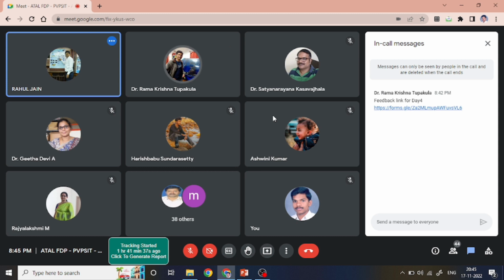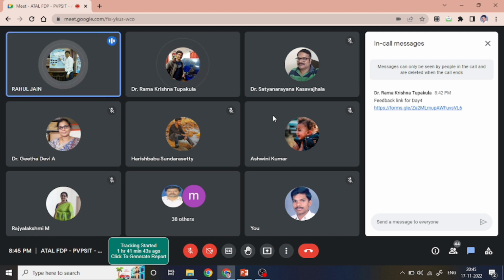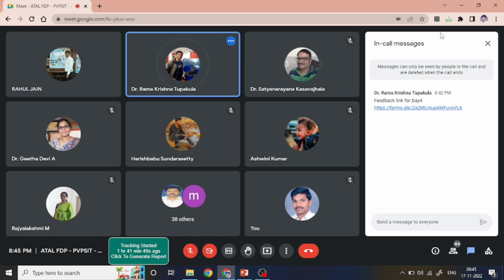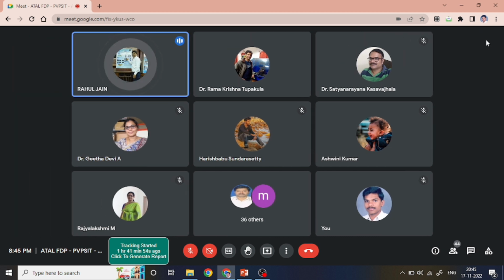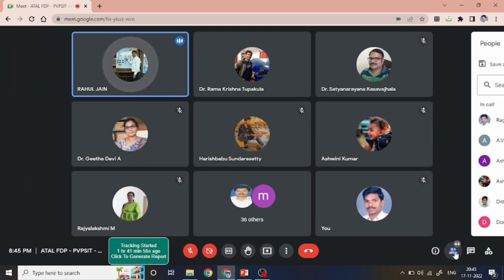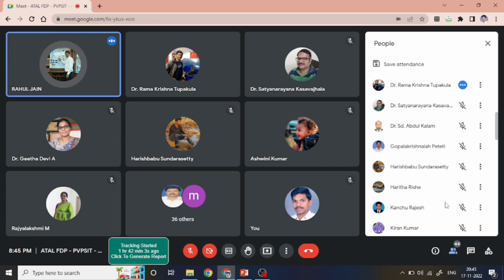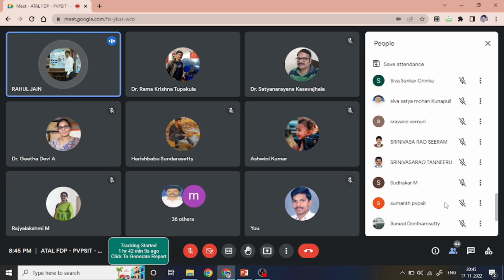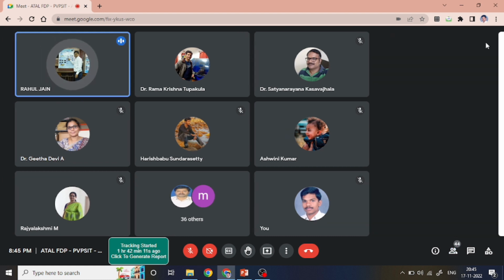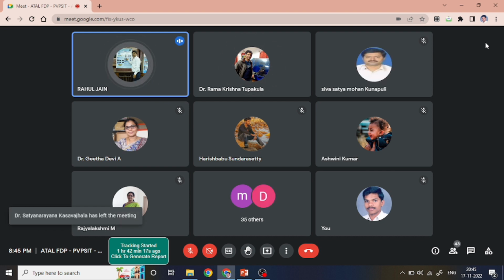So you mean to say additive manufacturing is best suited for solid complex geometries? Yes, it is. The only problem is the resolution. If your resolution is very low, then it creates a problem. Otherwise, yes, you can make it. I can share some photos with you, where you can see a lot of people have made this porous foam. But if the metallic part is very thin, then the best option is powder metallurgy, where the sintering could be by any mechanism.